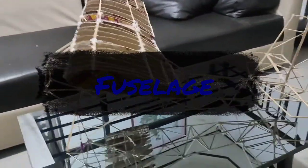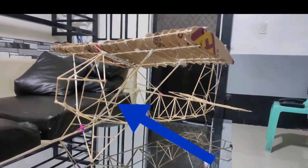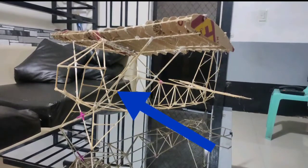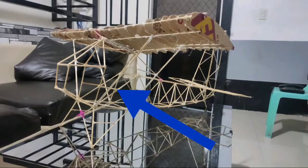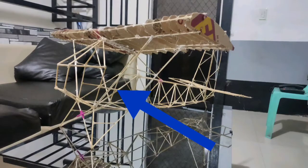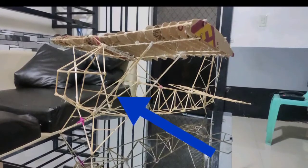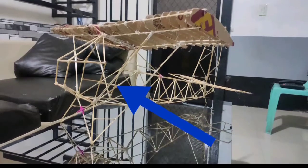First, the fuselage. The fuselage, with its long hollow tube that serves as the airplane's body, is one of the most important aircraft components. The fuselage structure of the aircraft model I designed is of the truss type or framework type. Many lightweight aircraft do use welded steel tube trusses in this form of construction. Steel or aluminum tubing is used to build the truss-type fuselage. Welding the tubing together into a series of triangular forms known as trusses provides strength and rigidity.